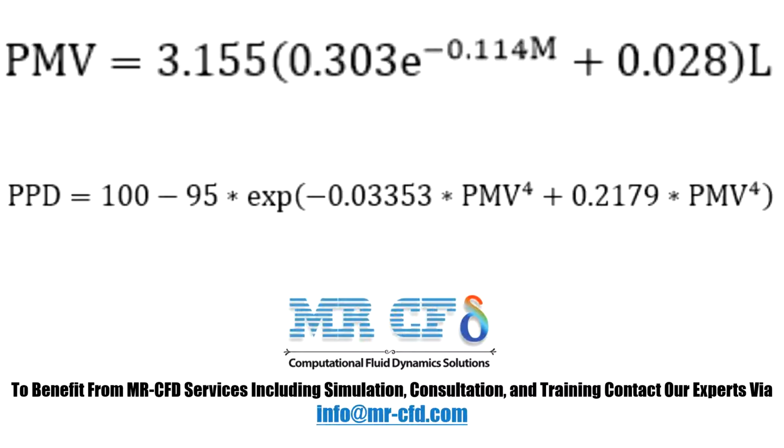There is also a fundamental relationship between the predicted percentage dissatisfied, or PPD, and a thermal environment as a function of PMV. As the PMV goes to +3 or very hot and -3 or very cold, the PPD increases, meaning dissatisfaction increases. While moving to 0, the PPD decreases and dissatisfaction also decreases.